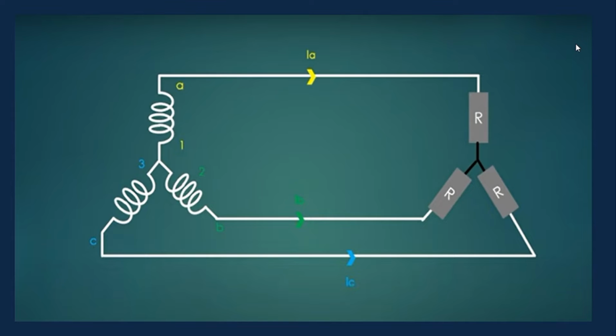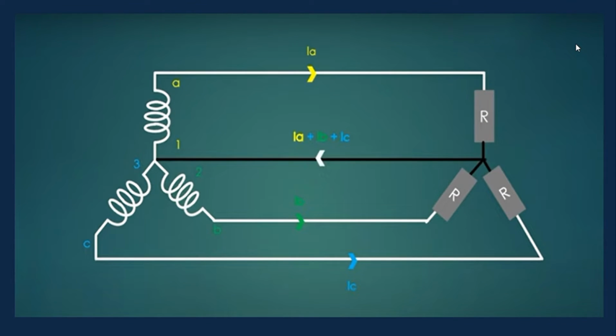The circuit shown in the figure is called a three-phase three-wire system. The generator and the load are said to be connected in WYE as it resembles the letter Y, or some people call it star. The figure shown is the three-phase four-wire system. The neutral conductor can be the same size or maybe slightly smaller than the other conductors. The three-phase four-wire system is widely used to supply power to commercial and industrial customers.